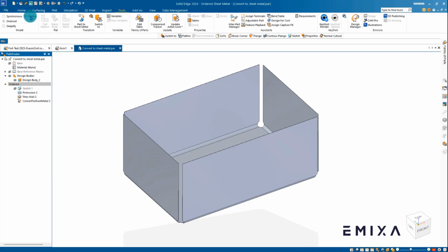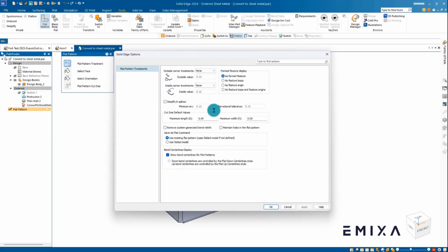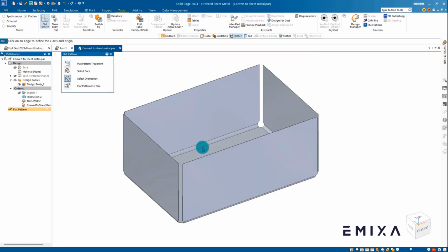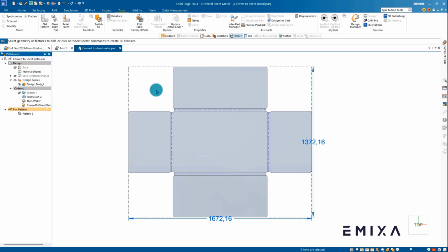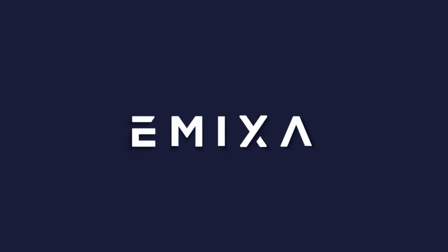These can also be flattened, so again on the tool tab we choose the flatten command, and we can choose any kind of corner treatment. So I'm going to do a radius, a much bigger radius just so we can see this on the corners. Normally you do a tiny radius just to make it safe. And you can choose this for the outside and the inside. That's then going to add that once we've done our flat pattern. So you can see we've got our blue bend lines on there and our flat pattern blank sizes on there.